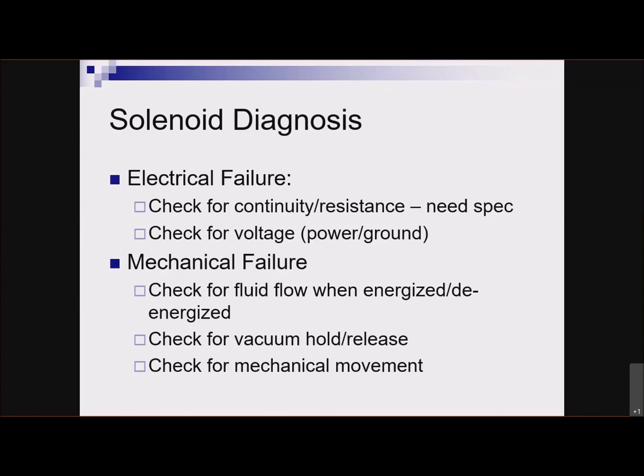And you can actually even check for the correct amount of flow, or at least that they're all the same, when it comes to a fuel injector, by just comparing that pressure drop. That's something, like I said, we're not going to talk about in detail. It's something you should have done in fuel and emissions. I think we did it in engine performance class 2 last year.